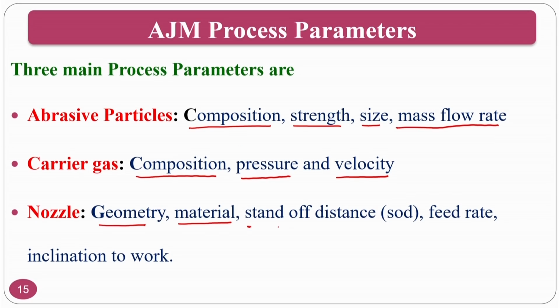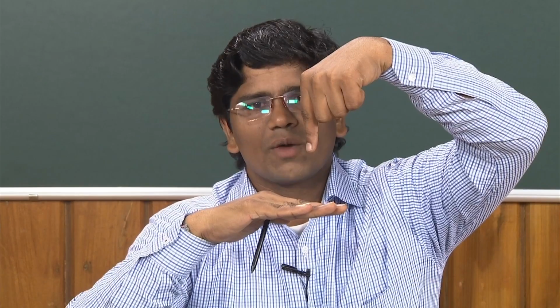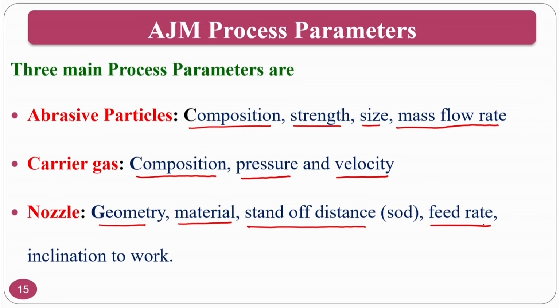The standoff distance is one of the things, that is nothing but the nozzle tip distance. Some of the books follow nozzle tip distance, some of the books follow standoff distance. Okay, the standoff distance and nozzle tip distance are both the same, which is nothing but the distance from the start of the nozzle to the surface of the workpiece. And the feed rate, at the same time inclination to the work. So, whether you want to go for certain inclination to the workpiece or whether you want to put it perpendicular,